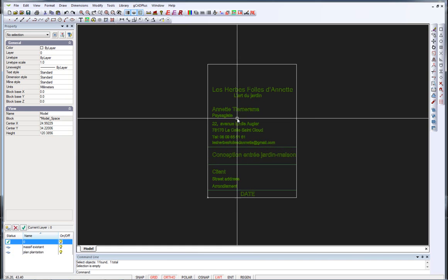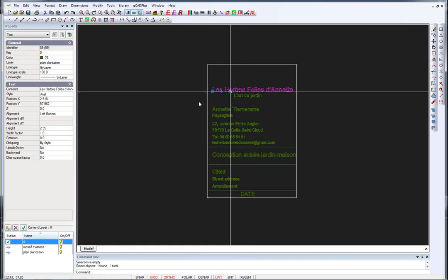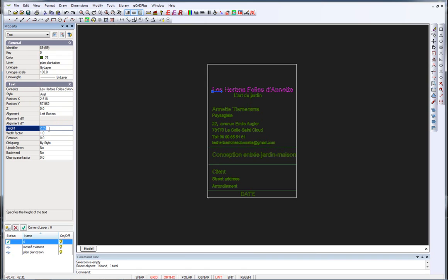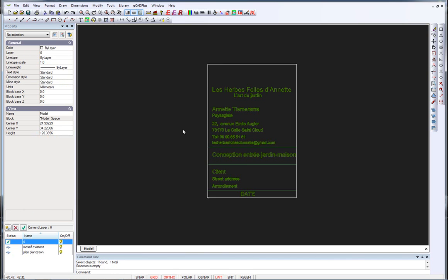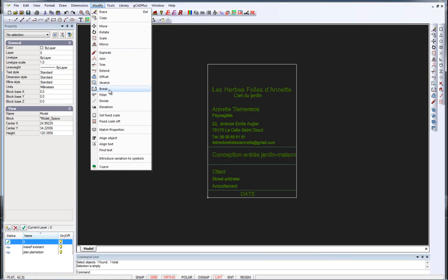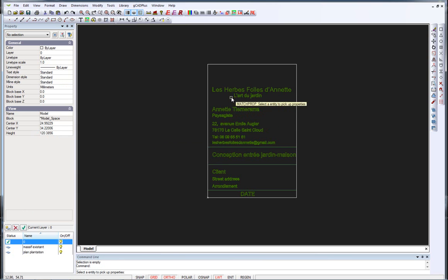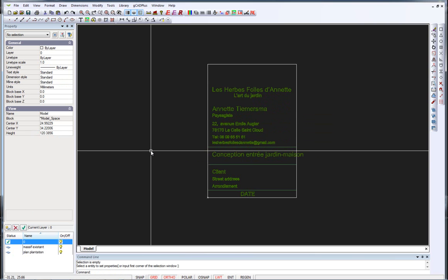But before I worry too much about that, I just want to check, pitching that text there, its text height, 2.55. Now, drafting standards in most countries would say, well, that should be a whole number, so it should be 2.5. So now that's 2.5 millimeters high. Let's unselect all, and now let's use the match properties tool. We know we've got that text, the 2.5, we'd want that 2.5, this one 2.5, so they now all match.